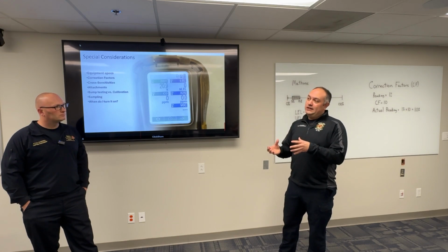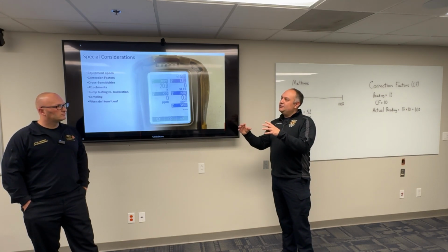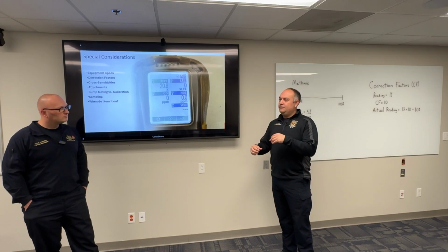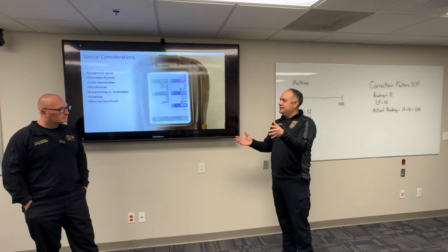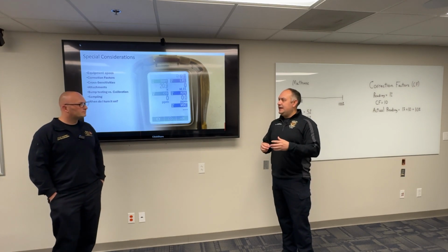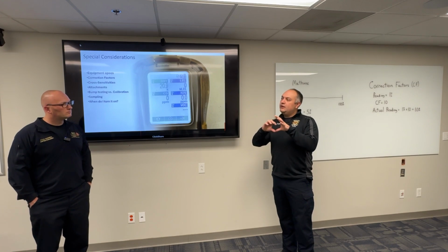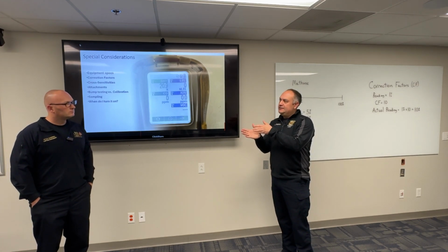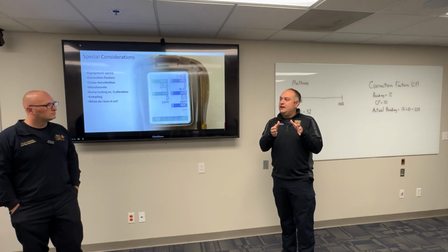If we're talking about calibration, that's where we've actually made the sensor accurate based on a known gas. If we use our CalGas, I think you guys maybe have the AutoRay 2 system, that's a known gas, and it will actually move or program the sensor to say, okay, we're a little bit off. We have some sensor drift, but we're going to move it over to where it's seeing the accurate amount of gas.